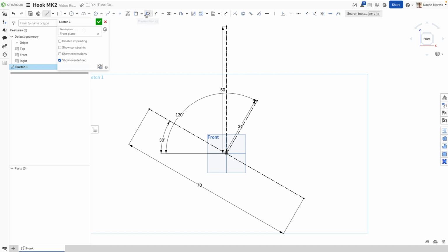So we're going to use line and construction sketch again, and that line is just going to come and be parallel to this line. So if that constraint didn't auto apply for you, feel free to apply it, and we'll make it 35 centimeters. So just recapping, 70 centimeters here, 35 centimeters here. That will be how we define our arc. This will be a 24 centimeter line. That's going to be how we define our slot.